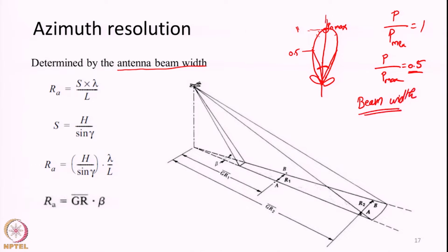So, essentially it is the direction covered by the antenna to transmit or receive back half of the power. This is very similar to the concept of full width at half maximum. Say the angle subtended by the antenna at which the power transmitted or received back is at least half of its maximum capacity. Okay. So, that will determine the beam width.